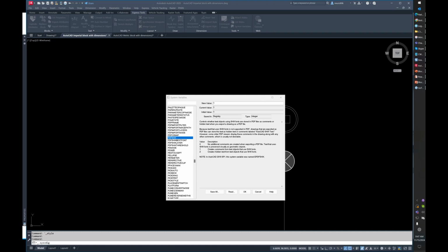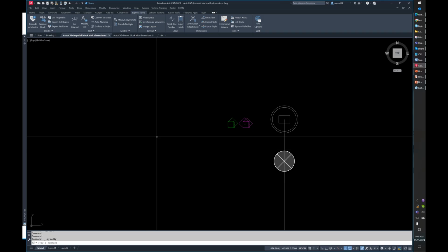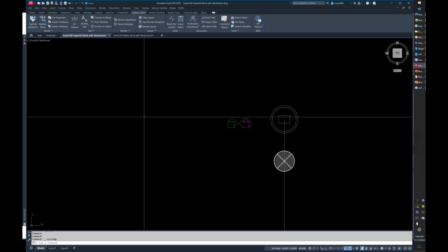Is there a way to make attributes on blocks that read correctly in different 3D views of the same block? Okay, so Robert, that's where you would probably have to create a dynamic block with different view states, where you're turning on attributes depending on the view state. So you've got attributes that are localized to top, side, front, bottom, whatever. Once you've set the block in and set the view state, you could go back in and do that. That would be the only way, because the attributes on the blocks are always localized to the Z of 0 and reading in the XY direction. You can change those attributes to be different, but you'd have to do that in a dynamic block with view states. That's probably the only way you're going to get that to work correctly, or label it after, which obviously you don't want to do.